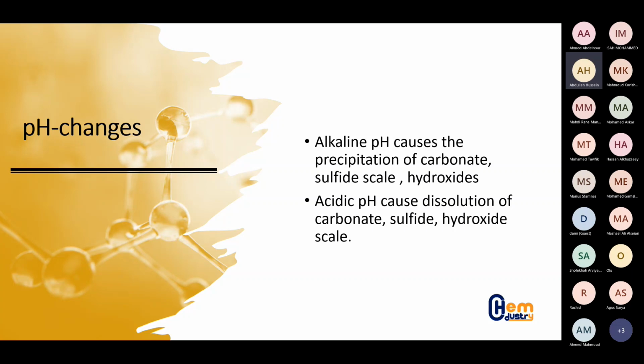There is a case when some operator tried to solve an H2S problem in their system. So they injected a production treatment chemical. It was a triazine. And because of the high pH of that chemical, that caused the calcium carbonate to deposit. So you have to be very careful whenever you add any chemical. You need to understand your production fluids and the possibility of scale to form.